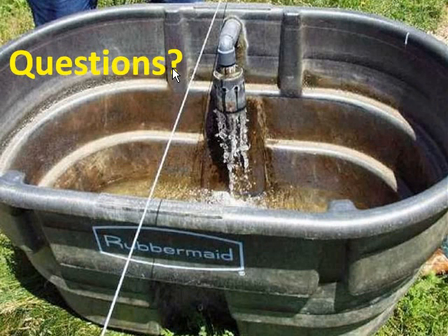Well, I would suggest that depending on where you are, you're going to need to test water from most sources. Municipal sources you're probably not going to need to test, and wells, depending on your location, you're probably not going to need to test. But some wells, sometimes you can have shallow wells. Those kinds of wells you're going to probably need to test. If you're in a coastal area, you may have some saline. You're going to need to test those.